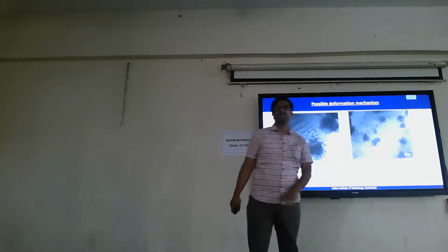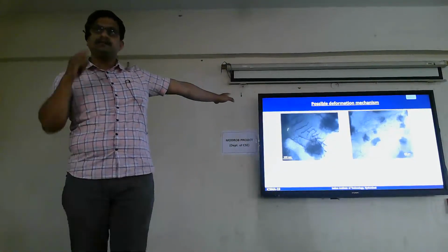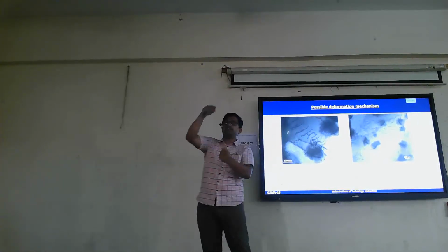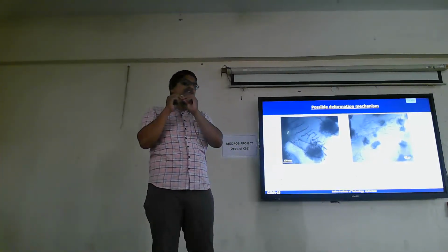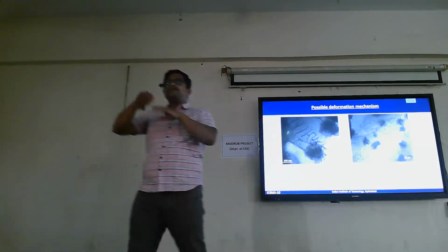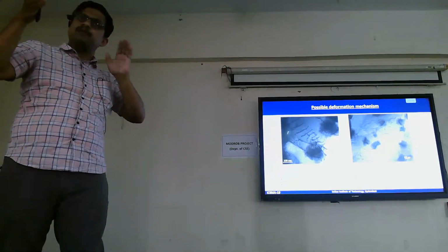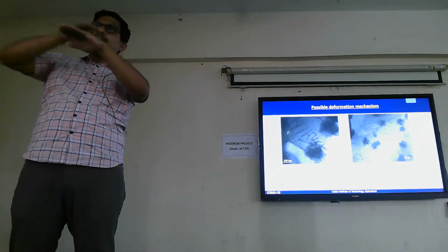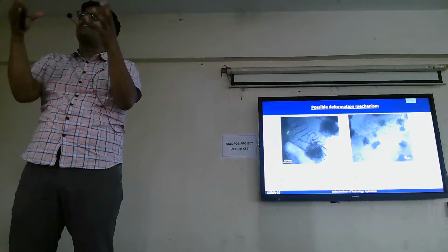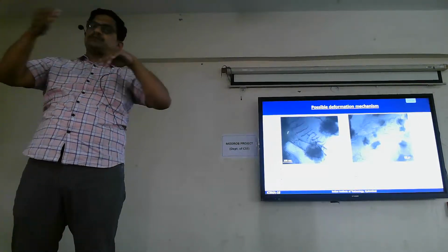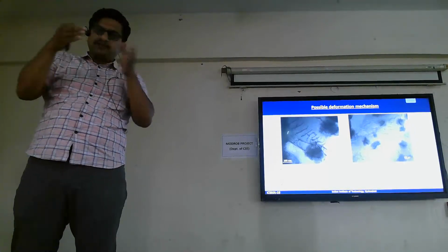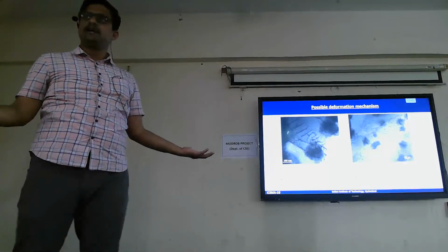These are the dislocations seen in the TEM. I tried to see how the dislocations are arranged in the material after deformation. After deformation, we took the sample from the gauge portion, and using TEM, the dislocations are equally spaced. If climb is the slowest process, dislocations will come and move close to each other for the climb process. Climbing is difficult, because deformation takes place by glide and climb, as I showed earlier. So then you see dislocation networks. When glide is the slowest process, the dislocation is climbing up before reaching that, so my dislocations will be very widely and uniformly spaced.